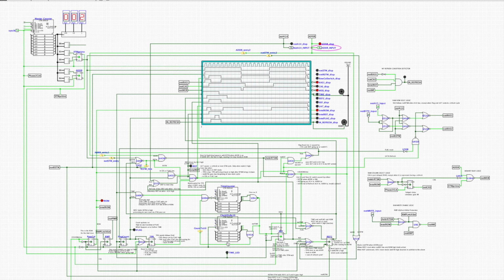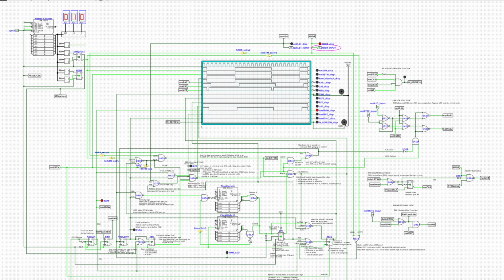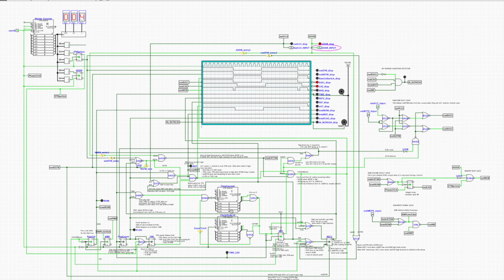The output of the divide by 10 triggers the other divide by 10, but it comes back here, it's mixed together, and it's held here. And the whole point of that is to generate variable times for refresh that align correctly with the memory cycle when it's addressed. So anyhow, you will hear when the time comes up for a refresh, it will have the low beep. And there's one coming up soon, right here.